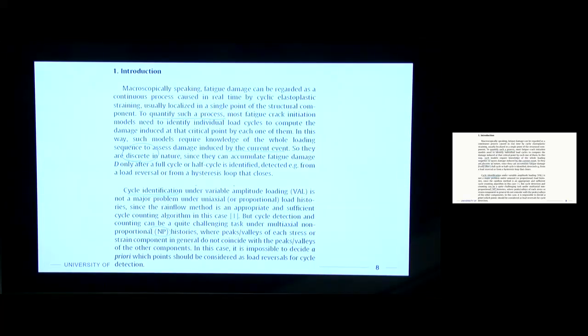So imagine a multi-axial loading, right? And then it's hard to look at the combined loading and say which points count as a load reversal. It's like if you did two rainflows on two different principal directions, and then you tried to put those rainflows together and see how they lined up. They often don't. And so this is what they're stating here.